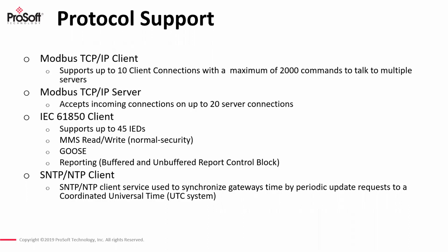with support for up to 45 IED devices. And when we talk about the 61850 side, there's a couple of different types of data messaging. Some of the most common is the MMS read and write, which is typical data messaging used for SCADA communication.